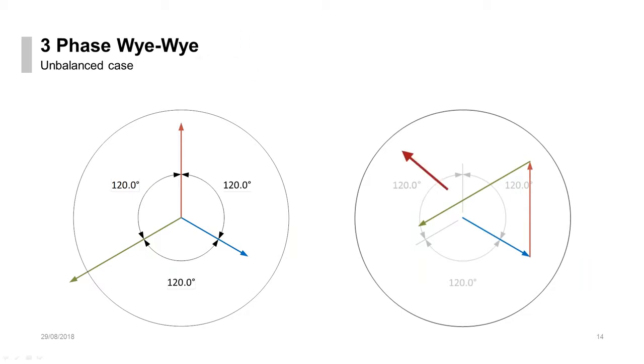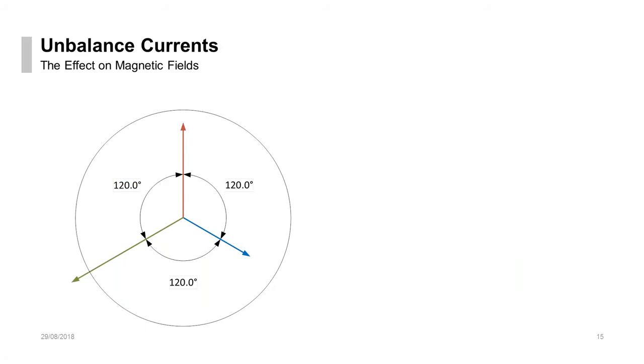So some of you may have heard of what they call a zero sequence voltage, and that's what the black arrow represents. That is the voltage or the currents that are being used to balance out this situation, so that way the sum is actually 0. And if we were trying to measure this, that could be considered leakage current, or there's a few other things that it could manifest itself as.